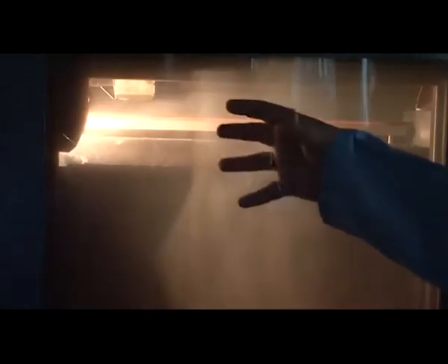The moment I enter demo, you can see that there is a square domain which the tool dispenser is going around. This is the domain where the workpiece printing would actually be done. So now I just continue. I go to the next option and continue and enter it, and now the whole auto calibration activity runs and the machine would be in automatic mode, and the whole printing would start happening, where there would be dispensing and writing of the particular shape slice by slice on the Mylar transparency film.